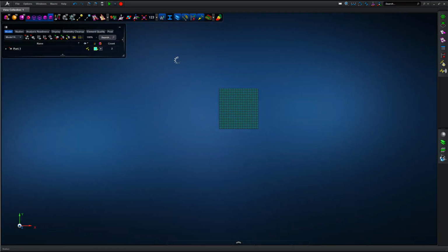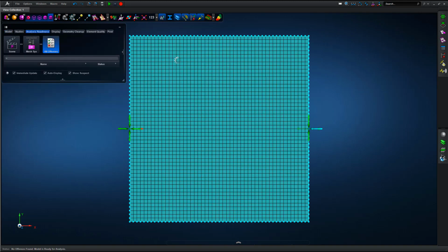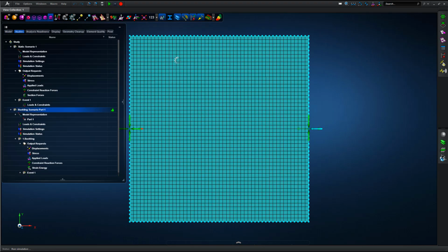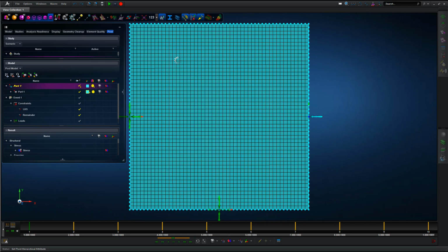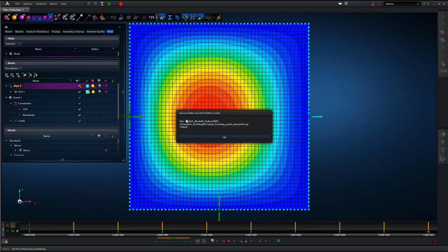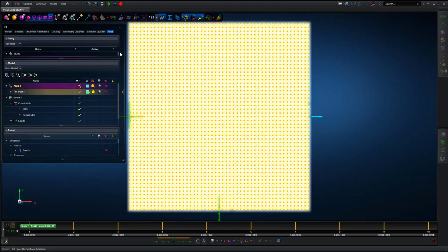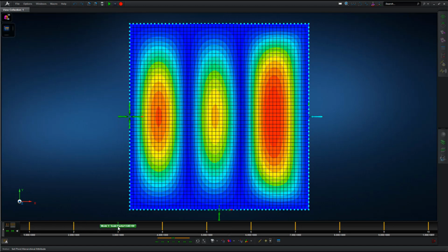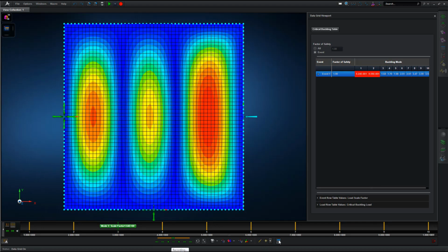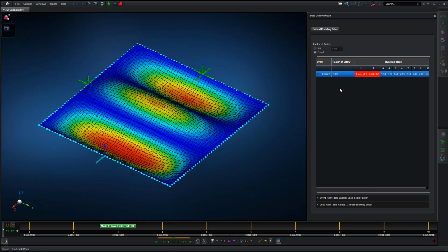So the model's stored, press the green button to run the macro, so the model's building, properties defined, loads and boundary conditions defined, and then if you look in the bottom left hand corner, the analysis is running, solving. This is a linear buckling example, so a standard MSC Nastran Sol 105 type approach. So the script is run all the way through to post-processing with no manual input whatsoever, and of course we could couple this with some of the other examples we've looked at previously, mid-surfacing, that type of thing, so we can add complexity and functionality to our scripts.